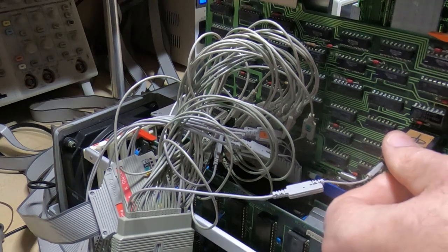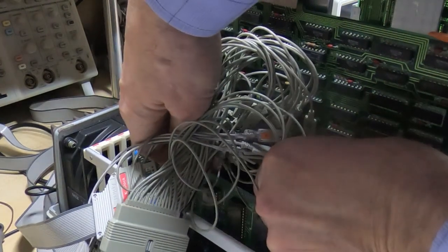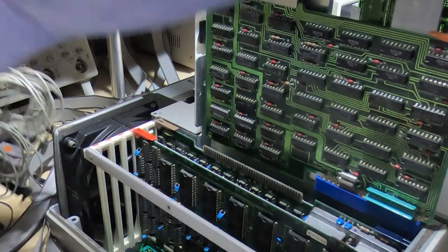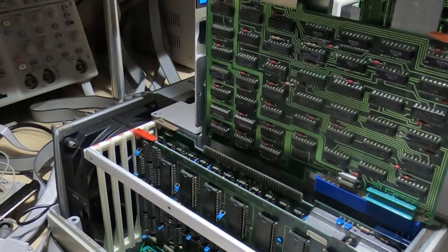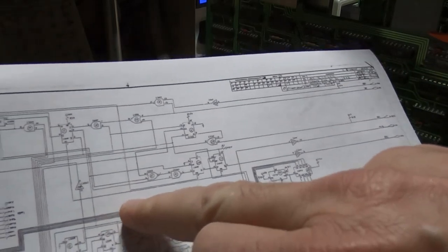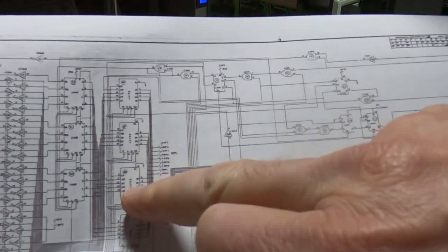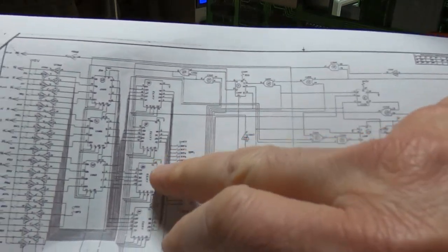So I'll disconnect the logic analyzer from the boards. Get that out of the way. And so, as I said, the most likely cause of this is a rogue control character coming through, because these are not doing what they're supposed to. Hope you can see this in a bit of an awkward angle here.